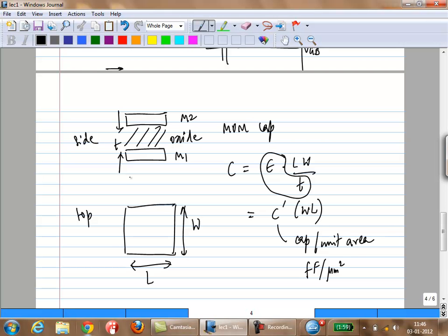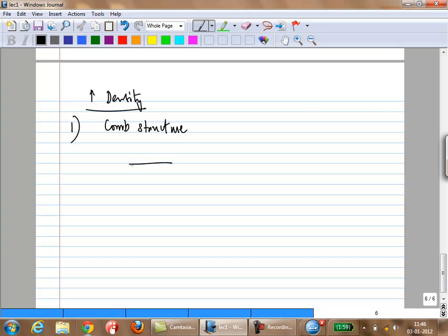the capacitance between M2 and M1. But you can also do this. You take 2 metal lines on the same layer, place them very close to each other, and you're going to have a parallel plate capacitance between them. Now the problem with this is that this dimension you can control, you can place them very close to each other, probably closer than the 2 metal layers. However, the area is the problem, because now this dimension is fixed, the thickness of the metal layer is fixed. So you might need a very large piece of metal to actually create this capacitance. But you can do things to improve.